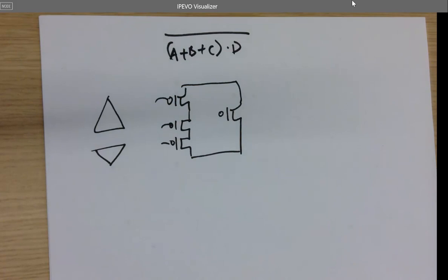I'm going to start with something. So first, draw the two rails. 4 transistors, so 5 nodes, right? 1, 2, 3, 4. We got 3 in parallel, 3 in series, and 1 in parallel. We got 1 go that way. What is a better way to do it? I believe you got maybe more traces in the top instead of at the bottom because you may route other traces in the middle. So I'm going to do that.